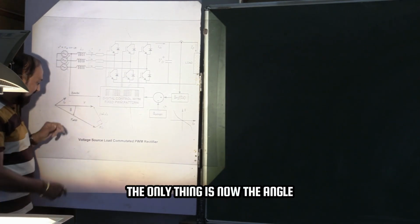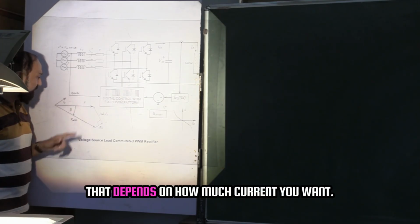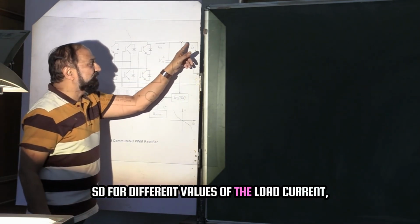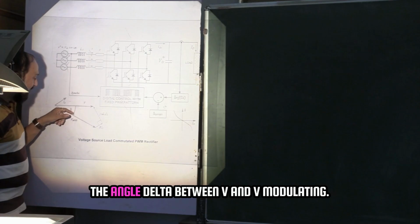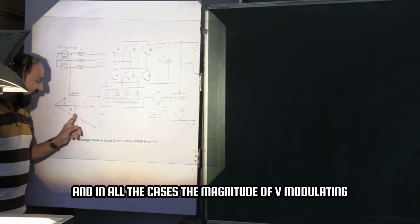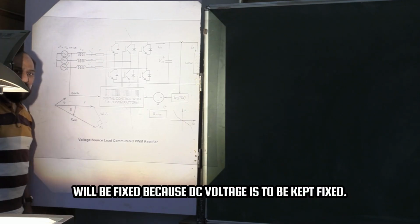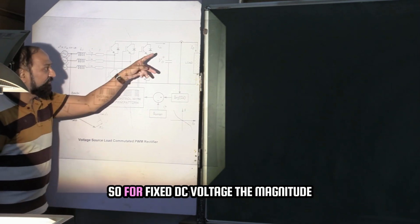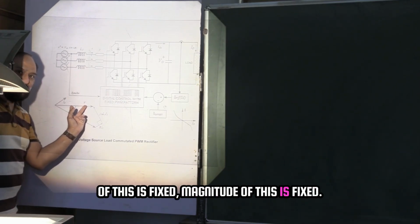For constant voltage VD, the modulating signal will be the same. The only thing is, now the angle between V and the modulating signal depends on how much current you want. So for different values of the load current, we can find out what should be the angle delta between V and V modulating. And in all the cases, the magnitude of V modulating will be fixed because the DC voltage is to be kept fixed. So for fixed DC voltage, the magnitude of this is fixed, magnitude of this is fixed.